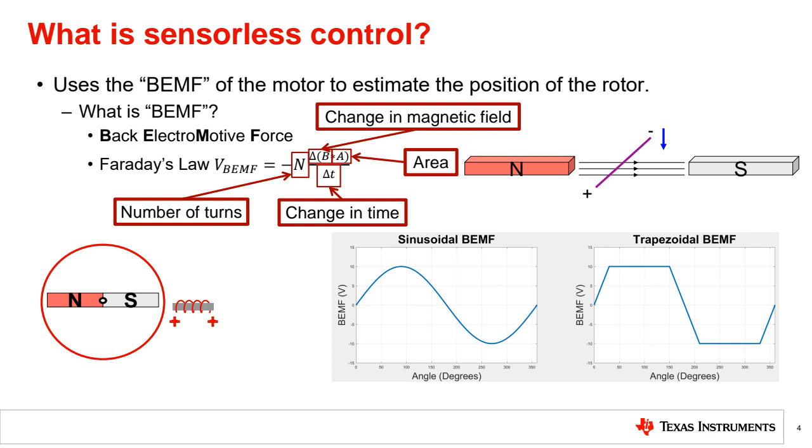You can see that as you spin the motor. Normally these are animations. In the animation, the motor is turned and it generates a sinusoidal back EMF. You can only imagine this sinusoidal signal going on to infinity. The magnetic field on the stator is changing in every turn, and voltage is generated on the phase of the motor due to Faraday's law.